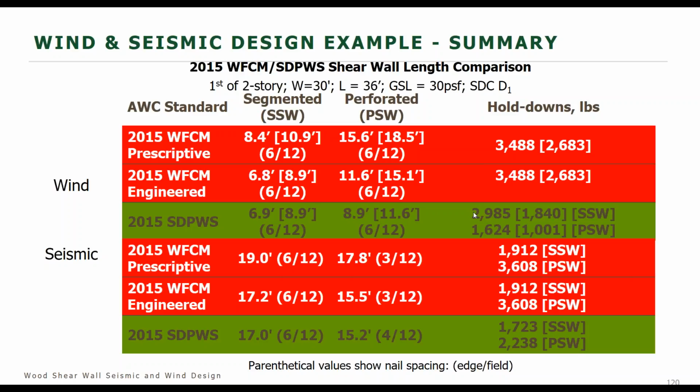You have a wind load, and then you have a seismic load. And obviously, depending on what part of the country, one would govern over the other, but we still have to check both, or we're required to. In some places, like Southern California, even though it's high seismic, depending on the configuration of the structure, wind could govern in some cases.